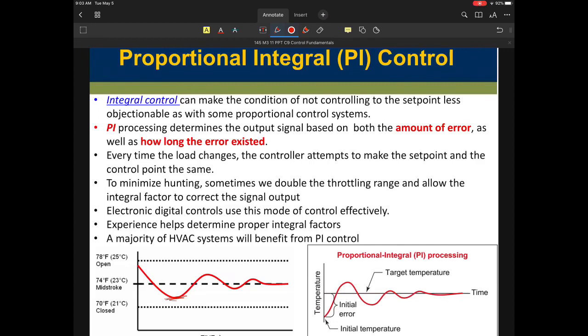So every time it reevaluates the algorithm and looks at the feedback loop, it asks, what are we getting? What is this temperature? In other words, oh look, we're exactly 2 degrees, 2.5 degrees away from set point. Well, let's go ahead and make a correction to that output so that we don't need to have it be somewhat proportional. So for example, I'm going to show this as an extra factor here.